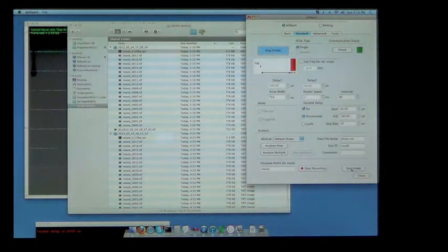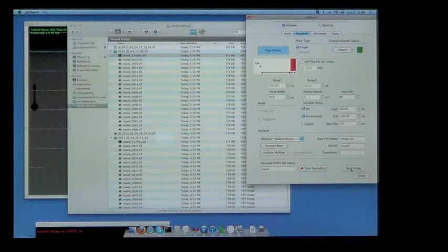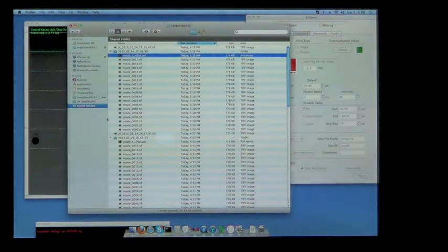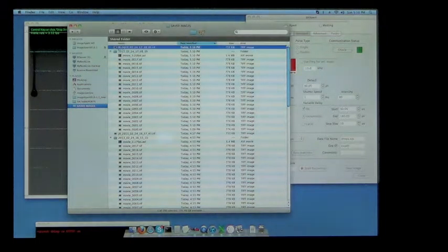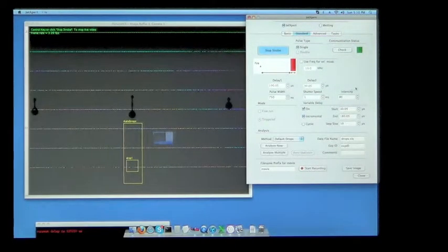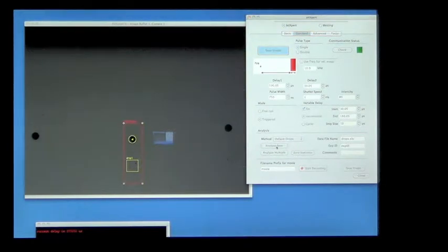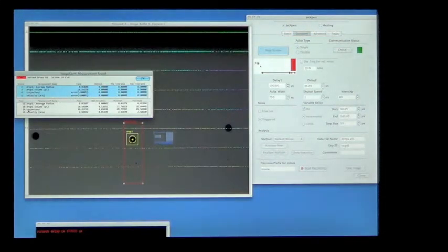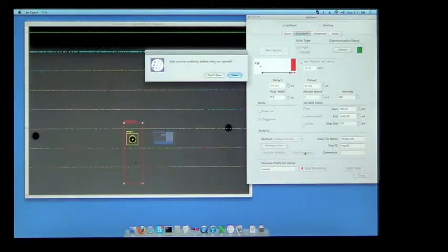Alternately, I can also save individual images simply by clicking Save Images. This image will appear in the same directory, Saved Images, with a timestamp. Once I've done a great deal of analysis, and I've switched inks or switched waveforms, I may not want the new measurements to be included in the old statistics. In order to zero out the statistics, I simply hit Zero Statistics.